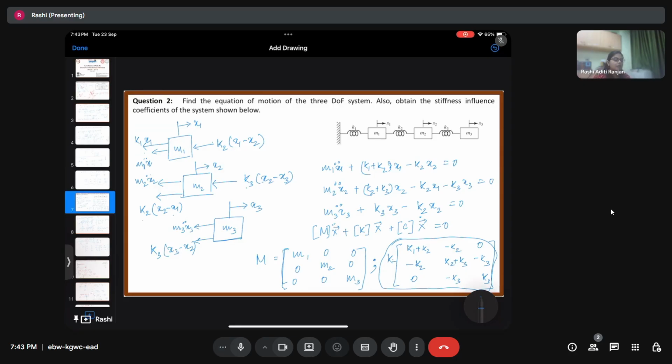So when we use the matrix which we obtain for a 2 or 3 degree of freedom system and find its eigenvalues, they are essentially the modal frequencies, and eigenvectors are nothing but the mode shapes.